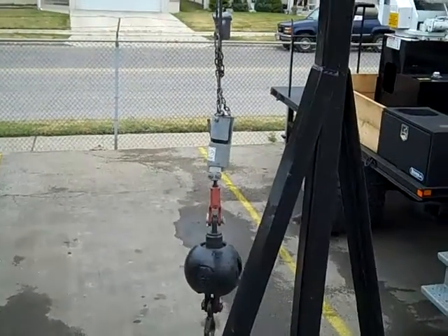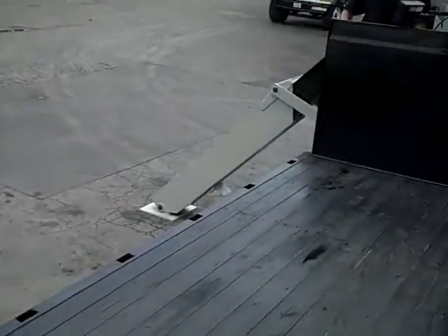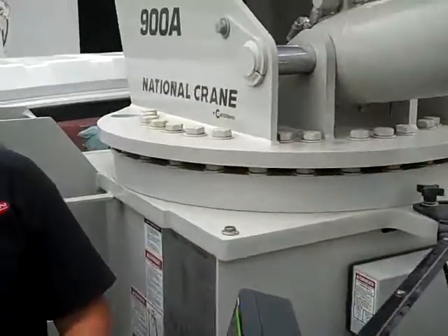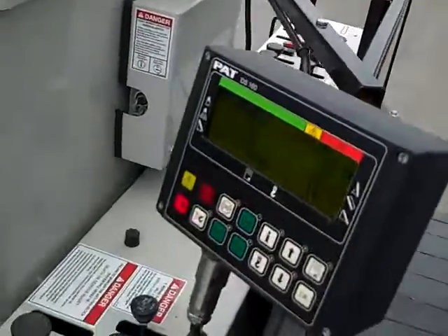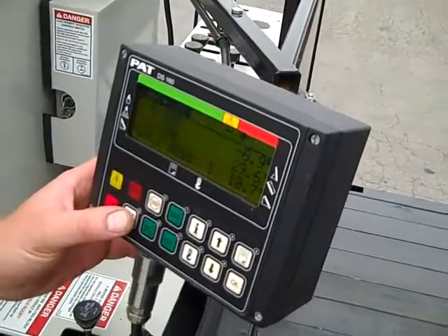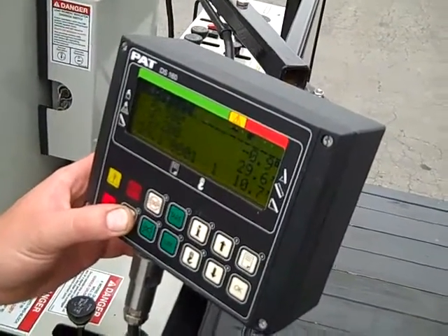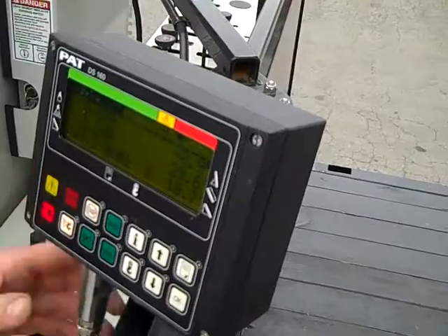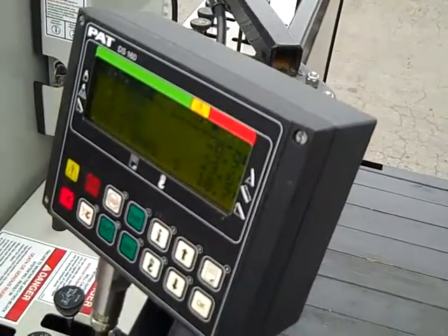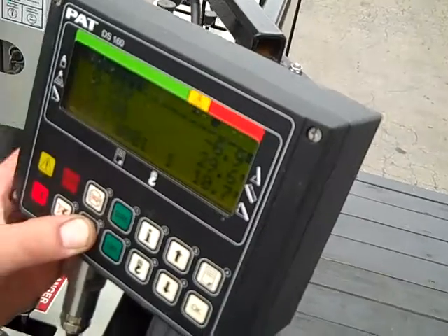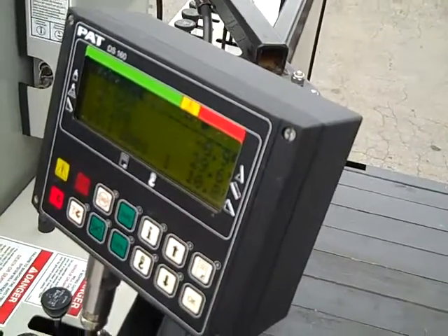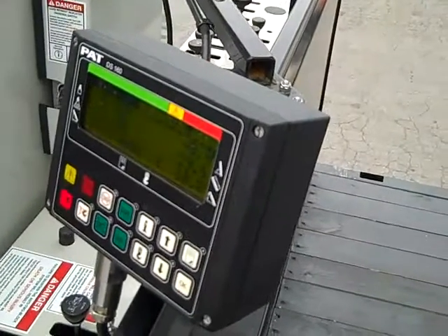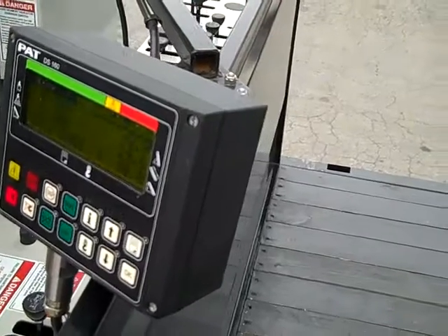Once the weight is lifted, you can hear the tone coming from the anti-two-block. The anti-two-block will not allow you to telescope out any longer or winch up. To bypass the anti-two-block so that now you can stow it, you just press and hold the override switch that Chad is doing now. You'll still be able to winch up, but the alarm is still going. If you wanted to make it so that the alarm sound wasn't beeping, you would just have to press the number 6 button, and that would make it so that the sound is not going any longer. Correct. All you have to do then is just tie your load block down and you're ready to go, and then just reverse the procedure coming out, turning off all your switches inside.